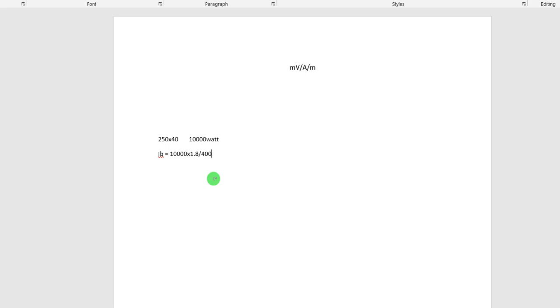So single phase of 230 volts will not survive voltage drop within this distance. I repeat, we choose 400 volts for the design because 230 volts will not survive voltage drop at the considerable distance of 500 meters.